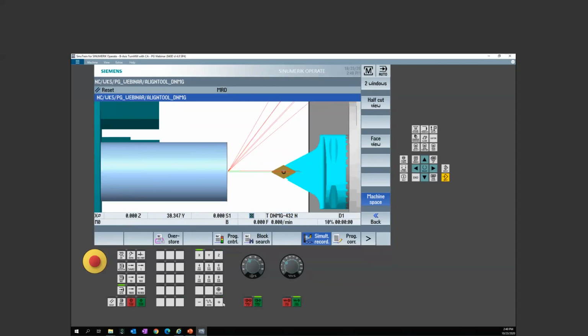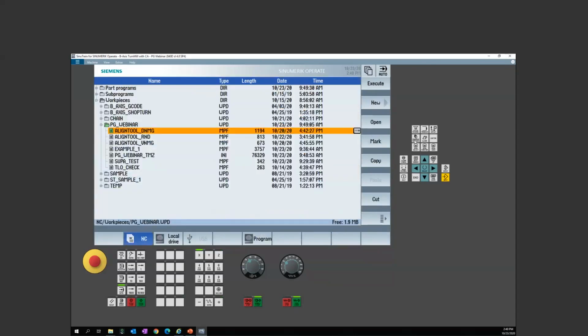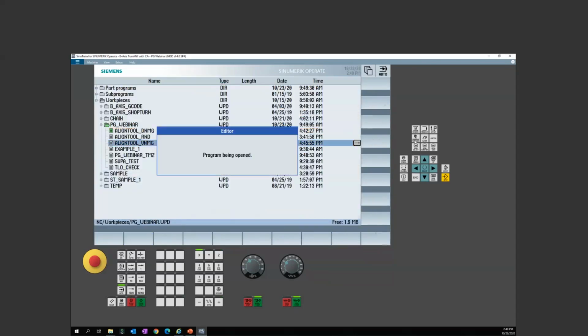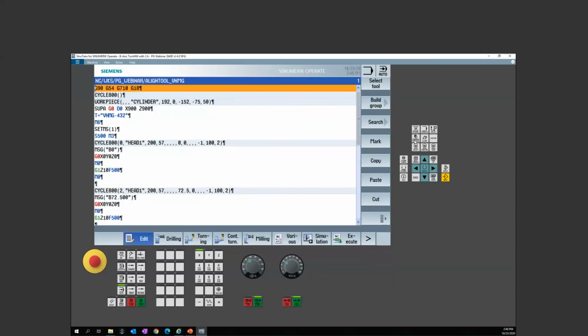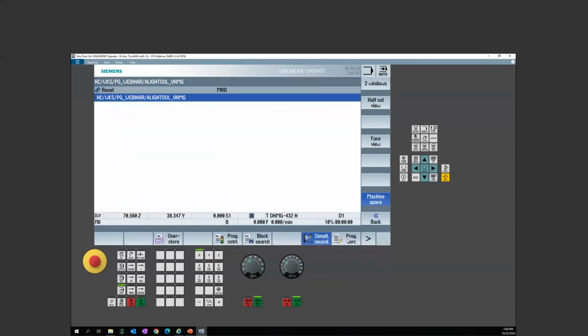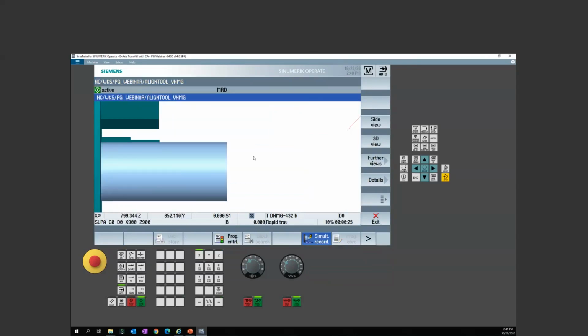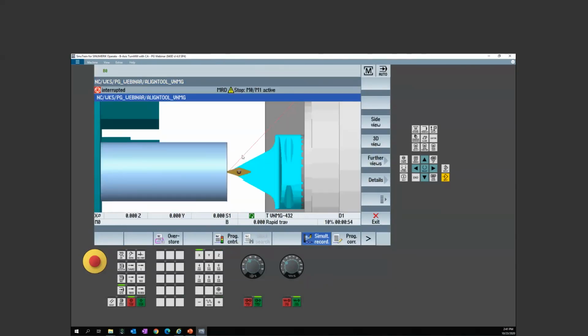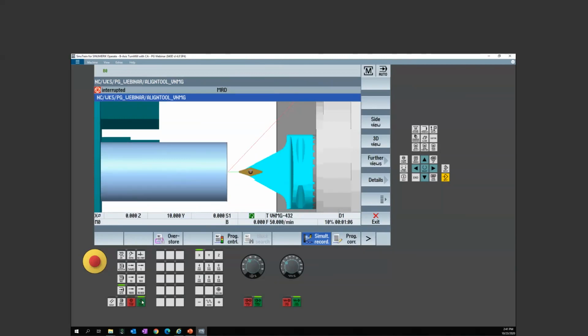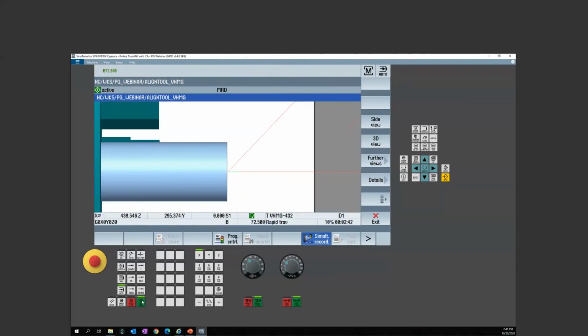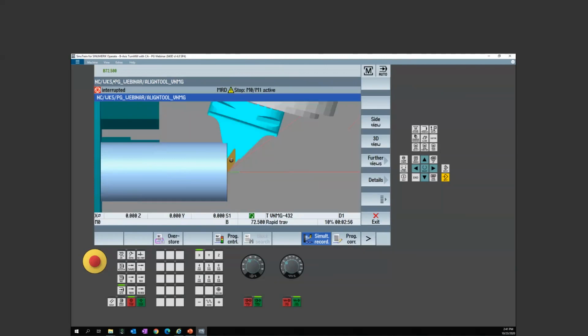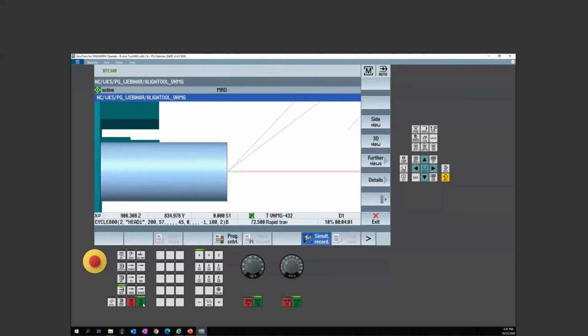So if I take a look at our VNMG program, I've got one right here. This is going to be a 35-degree insert. Now if I look at it, we can go right to our fancy simulation and run it. Now it's taking, again, half of that angle. So there I'm in a cutting edge position 7. But now, since I have more room, because it's only a 35-degree insert, I can go all the way up to 72.5, or I can go all the way down.